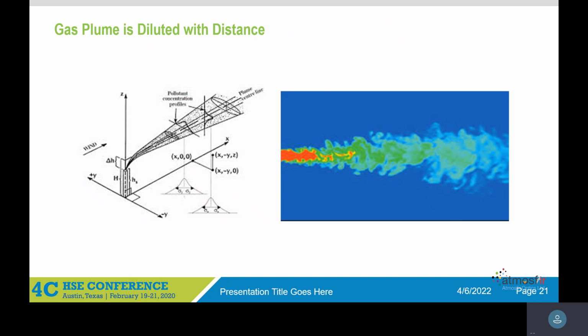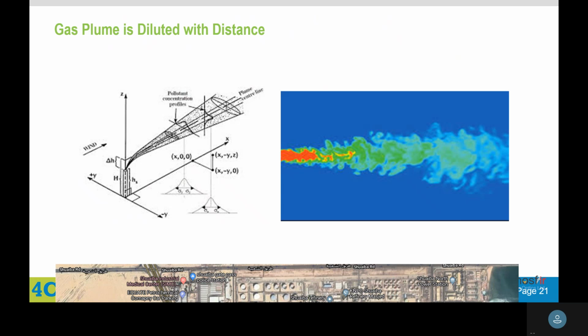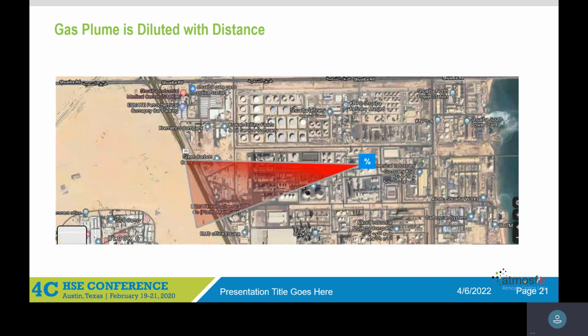One of our clients in the Middle East wanted to do what we call the holistic solution. The holistic solution says in the pipe, we've got concentrations of percentage or ppm. Usually it will be something like 30% or 100% ethylene oxide. So near the source, we're talking about percentage or ppm, but by the time it comes to the fence line, we're talking about ppb or sub-ppb levels. And that leads to different technologies.